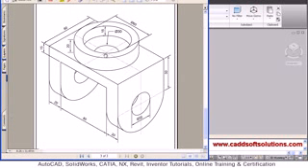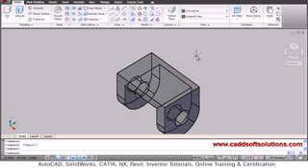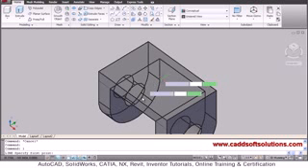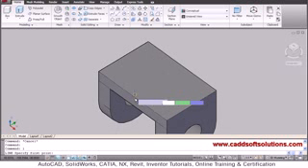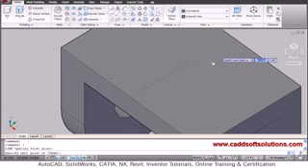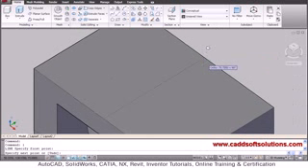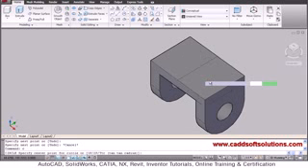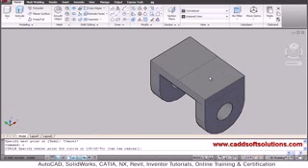So here is a circle of 80 diameter outside. So we will create a circle. So we will create a line, reference line from mid to mid. So from mid of this line to the mid of opposite line. And now here we will create a circle of 80 diameter, 40 radius. So just say circle and give the midpoint and give the radius of 40.